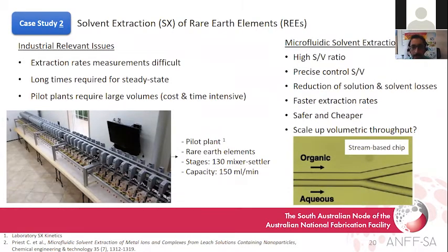The bulk solvent extraction method is common. It employs a mixer settler. The aqueous and organic phases are combined and vigorously stirred to form an emulsion. At equilibrium, mixing stops, and the two phases are separated by coalescence based on the difference in the density of the two phases.